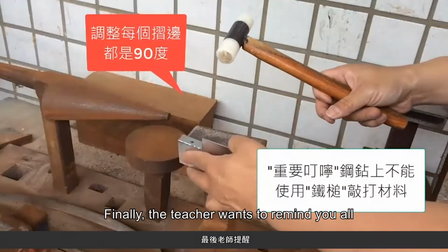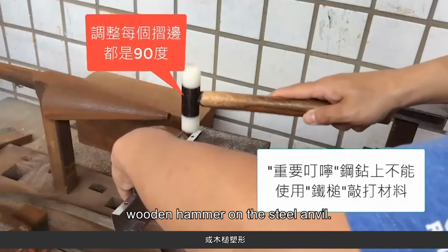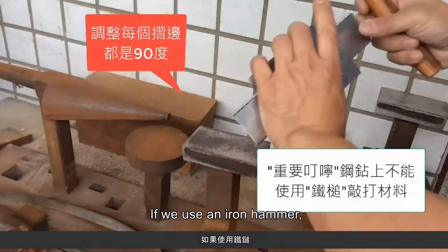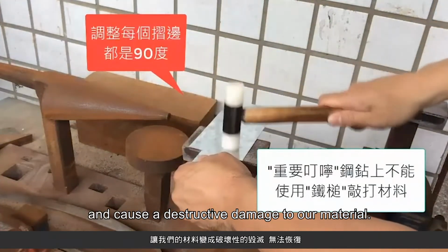Finally, the teacher wants to remind you all that we must use a PVC hammer or wooden hammer on the steel anvil. If we use an iron hammer, it will cause the stretching of the material and cause destructive damage to our material.